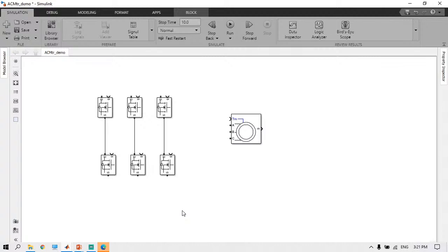And again this inverter you can connect with a rectifier. By default we cannot get a DC power supply, so from the AC power supply only we can get the DC power supply. But in the simulation we can use the DC power supply, not an issue. But in real-time applications you have to construct a rectifier and then a filter. Then only you can get a DC bus voltage. But for this simulation we are going to use the direct DC voltage as the input to this inverter.